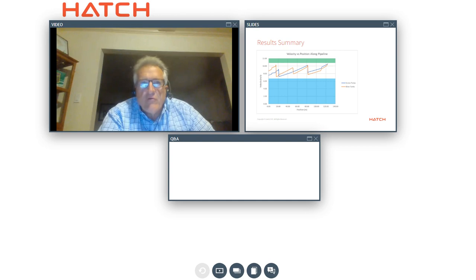And it's very critical that you step the line at the right location, not just to reduce pressure drop, but so that you always maintain sufficient velocity at the step point so you don't drop into that dense phase mode. And you'll see that in this solution, we're in a range of about 7 to 10 meters per second for that complete band of being in the two-phase flow.